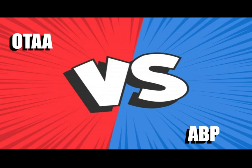So the LoRaWAN network server provides or supports two activation methods. The first activation method is called over-the-air activation, and the second is ABP, or activation by personalization. ABP involves pre-provisioning devices to operate on a given LoRaWAN network, and they're defined by its network ID. Devices are configured with network and application session keys, along with pre-allocated 32-bit network device addresses. The IP analogy of this scheme is a static IP address.